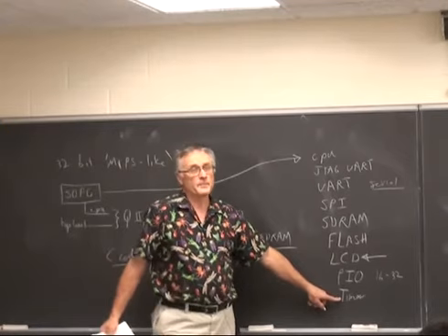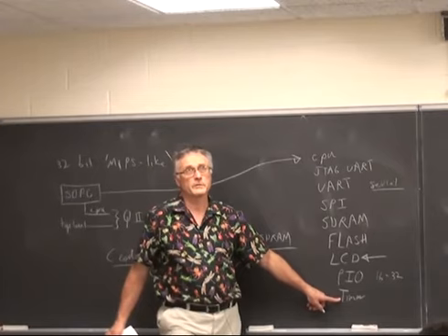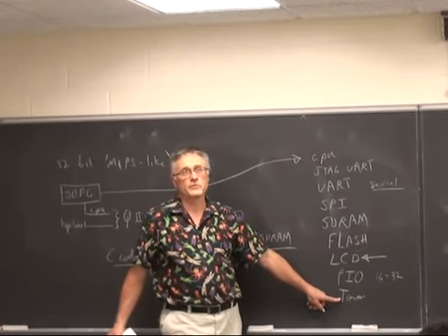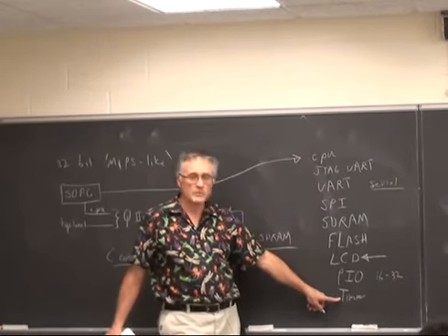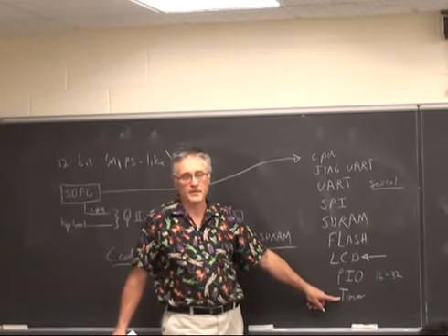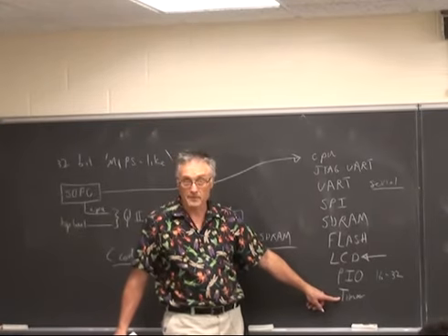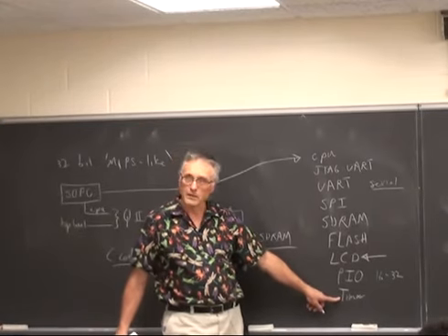The timer interrupts on this microcontroller take between 200 and 400 cycles to take the interrupt. So after the timer ticks and throws an interrupt, it's 200 to 400 cycles before your interrupt service routine starts to execute. It's a long time.